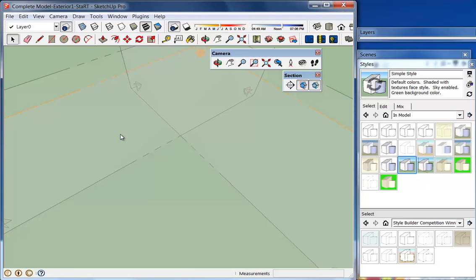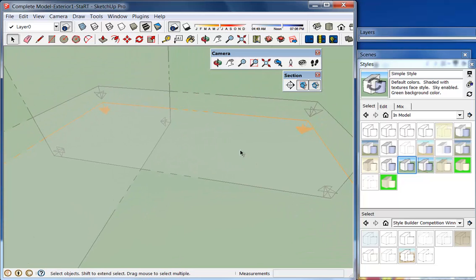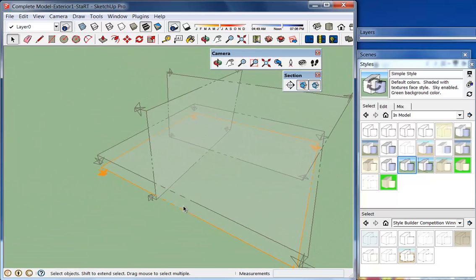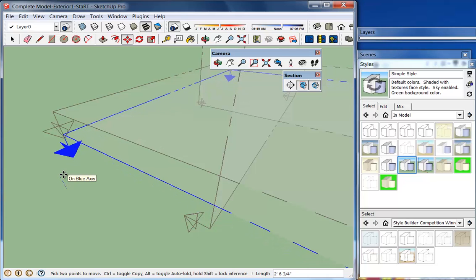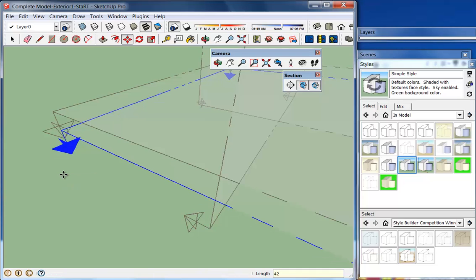So if I place my section there, right, now you can see the section settings turned on, right? This is at the bottom of those walls. What I want to do is I want to take that section. You can see the previous section that I have here. I want to take that section and I want to move it up. So you see it selected using the Move tool. Just click anywhere off the model and then pull along the blue axis. Use the value control box and just type in 42 or anything between 32 and 42. Okay.